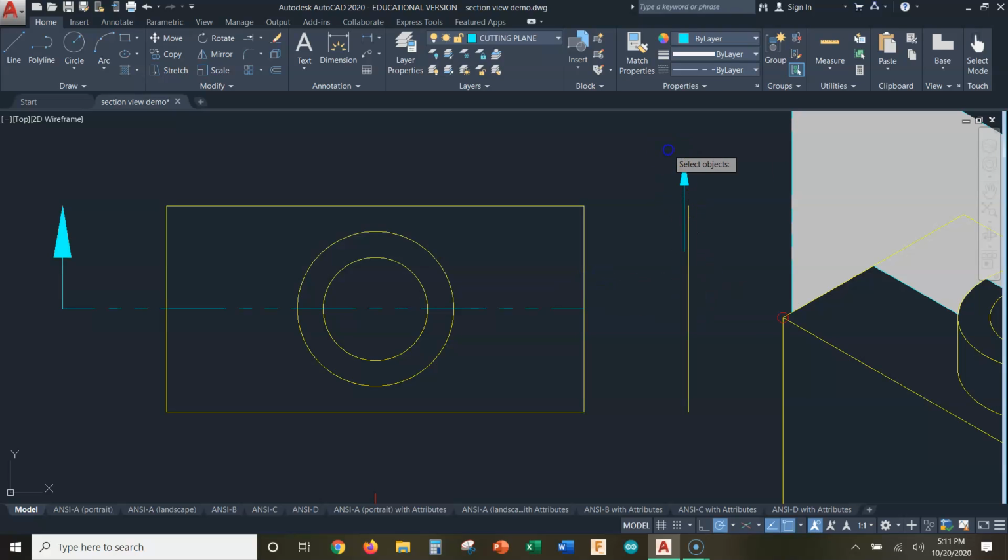And then I'm going to use the move command. I'm going to move the arrow and the line so that the tip lies right on that point right there. I'll erase my construction line. Now I need to extend this out there, so let me show you a little trick. I'm going to use the fillet command, but I'm going to use the fillet with a radius of 0, because a fillet with a radius of 0 creates, you guessed it, a square 90 degree corner.